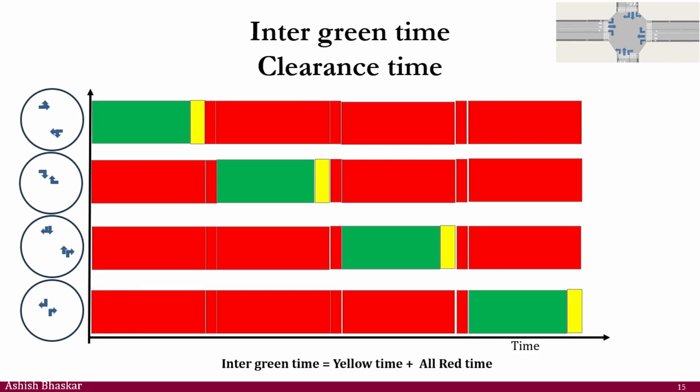So they use the word hold the red, meaning hold your all red for a longer time interval, right? And it takes the image also, and the bill goes to the guy that you have done the red light violation. Because you're not supposed to enter the intersection at this time. If you are the guy traveling here, you can enter the intersection at yellow, but your back bumper or the back tire of the car should not leave the stop line when you are here. If it leaves, you have the red light violation. I don't know, maybe you have 3 or 4 demerit points, and you might have a $300 or $400 fine.